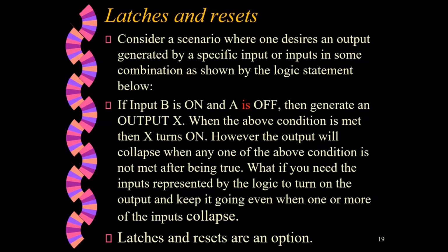The first thing I'm going to discuss is a latch. It's also called a reset because latches are used for resetting outputs. Simple case, I want to turn on a motor and I have a pulsed switch. That means momentary on, which we have discussed and seen how it is used. I turned on the motor with that pulse switch.